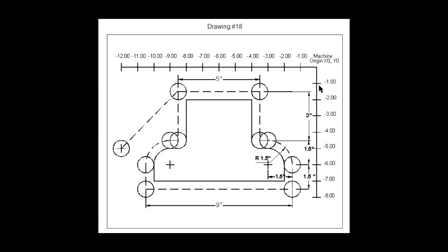And when you do that, you type in there, or write in, depending on what you're using, their XY coordinates. And then when you go about programming, actually writing the G code, it's a matter of putting the right code to go with the right dots so you can connect them all together. What we're going to be doing in the early parts of this program is learning how to develop those dots so you put them in the right spots. Then after that, we'll go about creating the commands to connect those dots in a way that's meaningful and makes a good part.